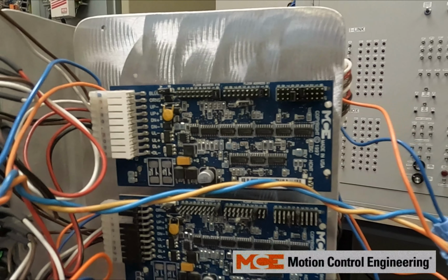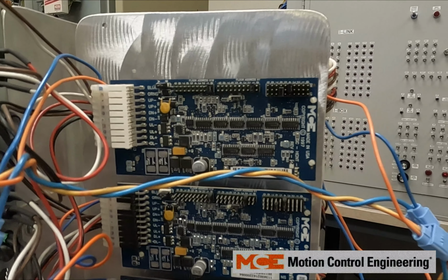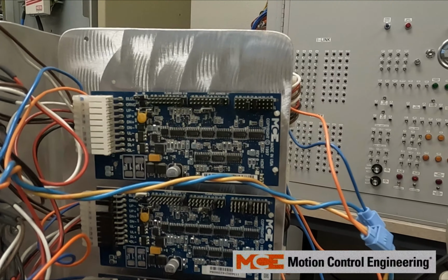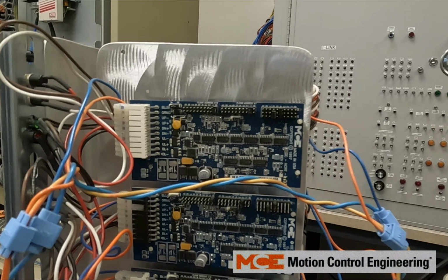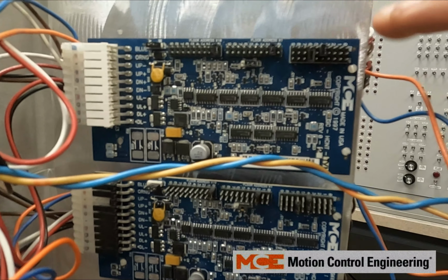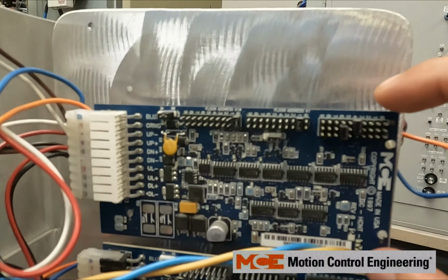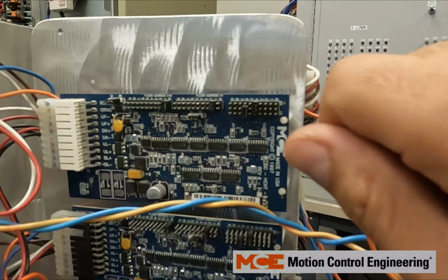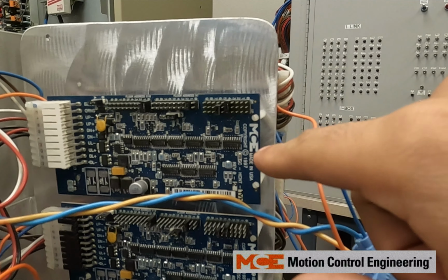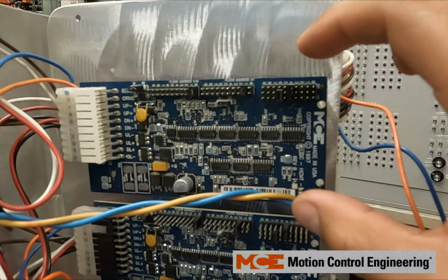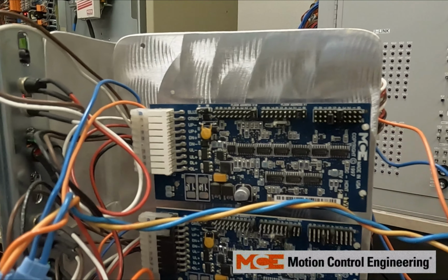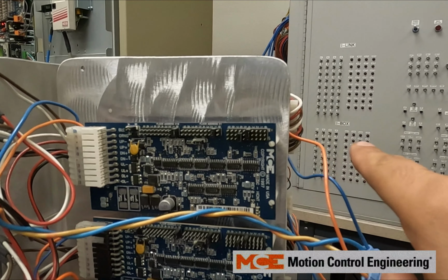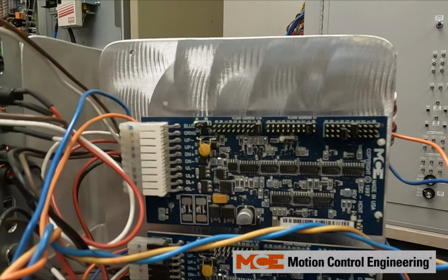So here I'm going to be explaining CFSS mode 1, as in VIP or hospital up call. For a hospital call, this is the board you will have behind the up and down push buttons. But if you also have a key switch there, you have another board just like this one, but that key switch for the hospital or VIP will go to another HCNT board, hall call node board, but with different jumpers.